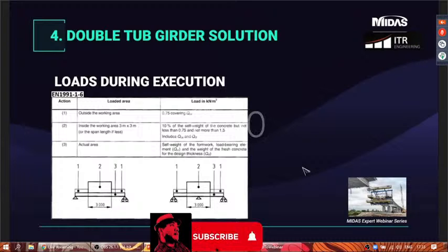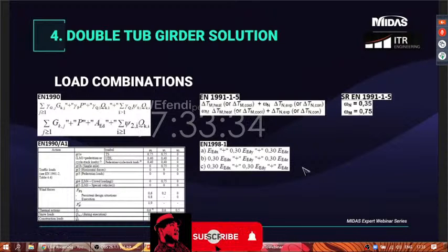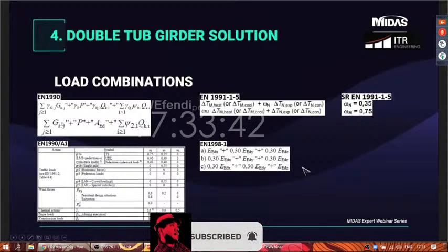Finally, we take a look at the load combinations considered in the model. Here we will show the Eurocode 0 ultimate limit state fundamental combination and seismic combination. Here we have the combination coefficients for road bridges from the national annex.